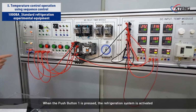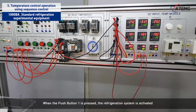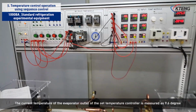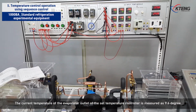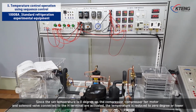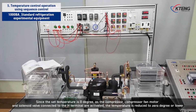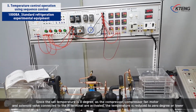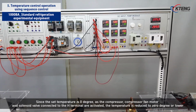When push button 1 is pressed, the refrigeration system is activated. The current temperature of the evaporator outlet of the set temperature controller is measured as 9.6 degrees. Since the set temperature is 0 degrees, as the compressor, fan motor, and solenoid valve connected to the H terminal are activated, the temperature is reduced to 0 degrees or lower.